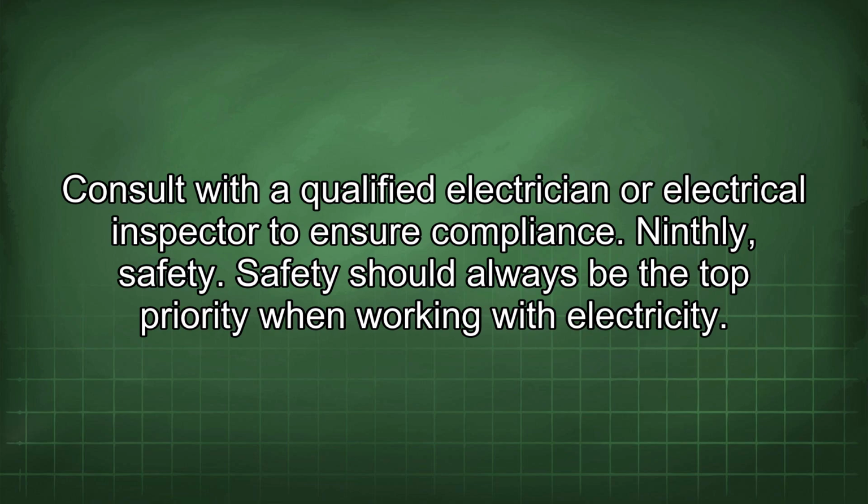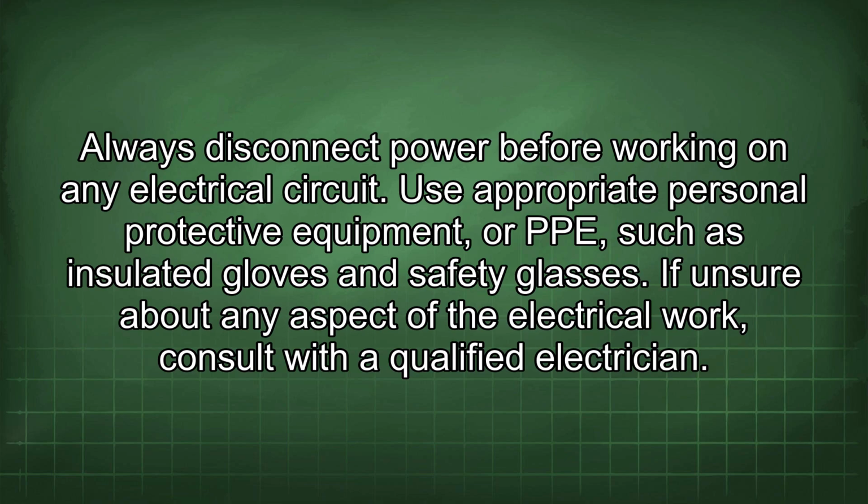Ninthly, safety. Safety should always be the top priority when working with electricity. Always disconnect power before working on any electrical circuit. Use appropriate personal protective equipment, or PPE, such as insulated gloves and safety glasses. If unsure about any aspect of the electrical work, consult with a qualified electrician.